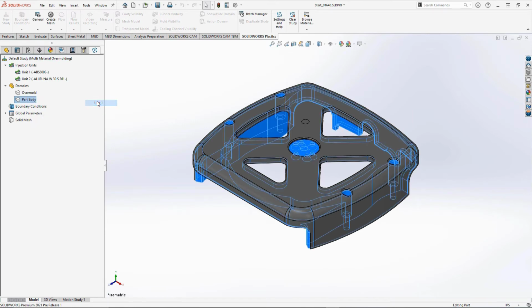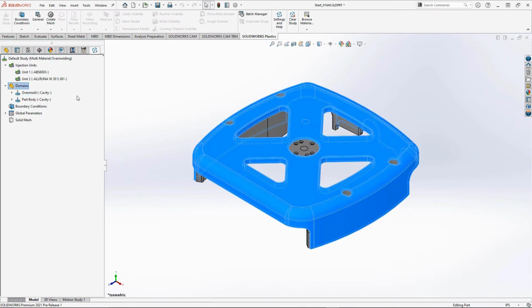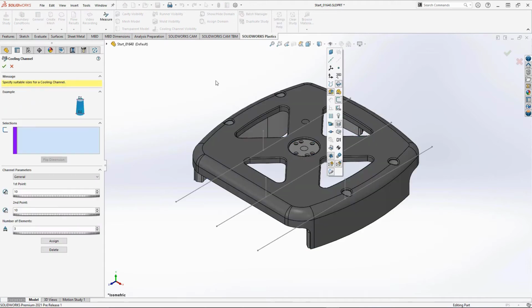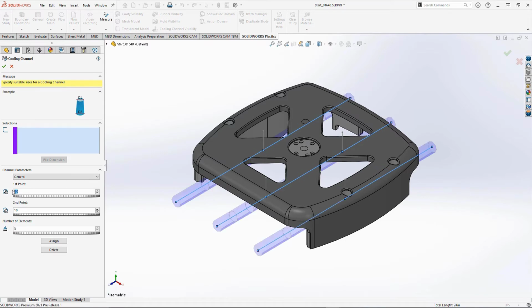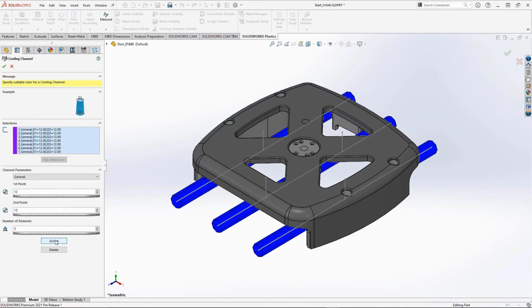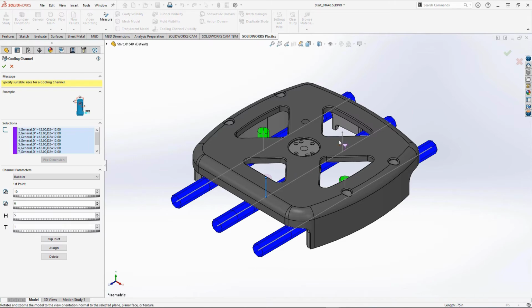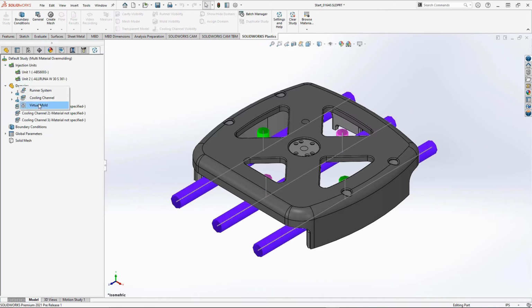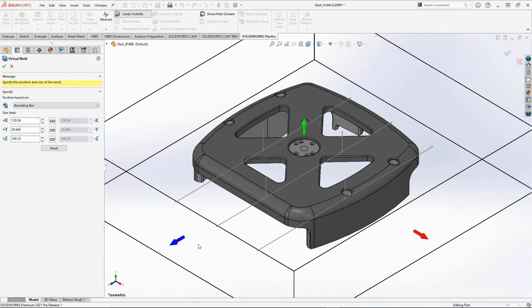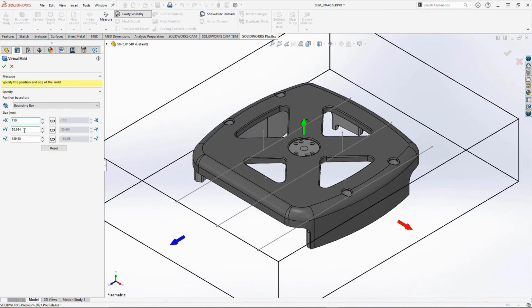And then I'll go through and start specifying my cavity domains for the parts, for the molds, and anything else that I might have already modeled. Now in this case, I didn't model the cooling channels, but that's okay. I can build those from simple sketches to save time. The bubblers, the baffles, everything's really easy to add, and it displays on the screen to make sure it's represented accurately. Similar to the cooling channels, the mold itself doesn't need to be explicitly modeled to be understood and calculated.